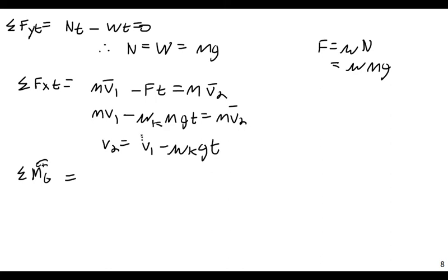So again, keeping in mind appropriate directions, I have F_t r, the moment of that force times t to get an impulse, equals I omega 2. I times omega 2. And if I then put in this here, F, again substituting F for mu mg, I get mu kinetic mg times r, or mu kinetic mg times t r.